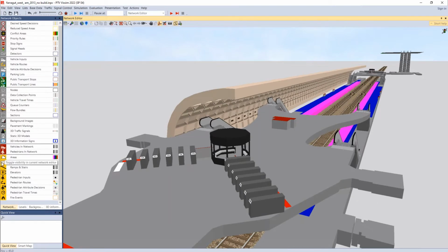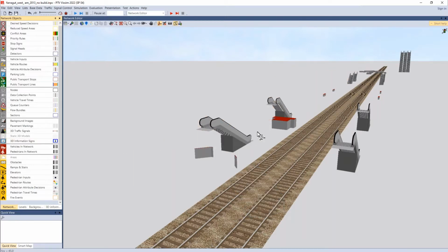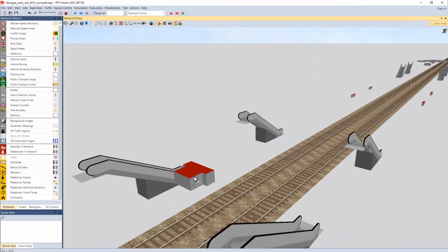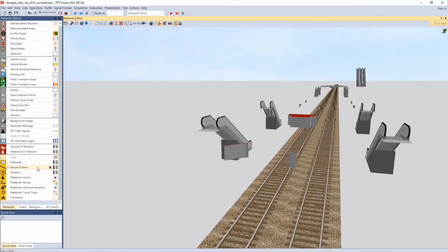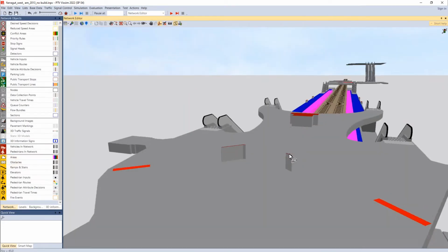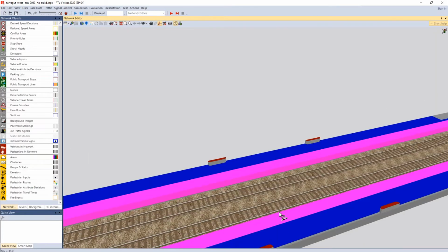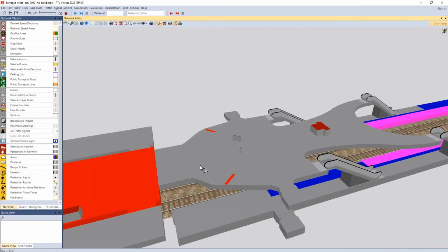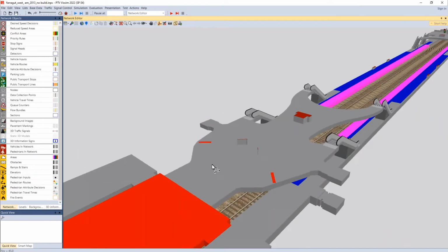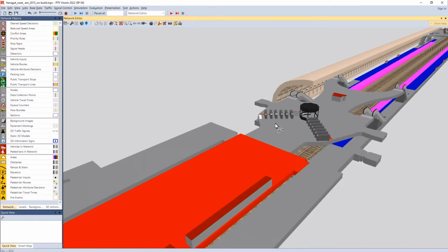But you can see that if I turn off the areas and turn off the 3D objects, we have a couple obstacles that are just hanging out here that are acting as kiosks or walls, or maybe we have benches down below that are making pedestrians avoid them. So again, you'll draw out your obstacles to act as negative space that pedestrians have to avoid.